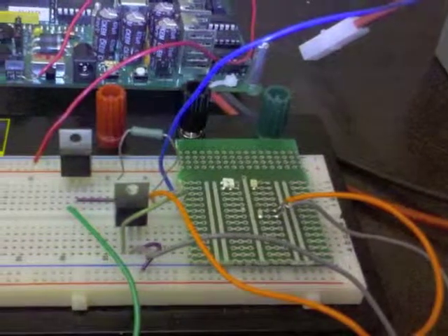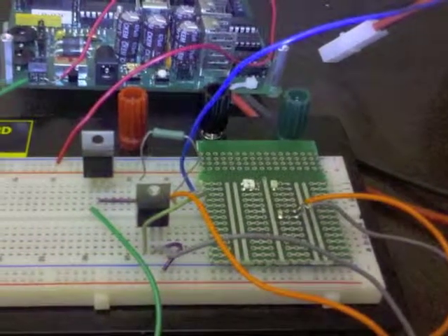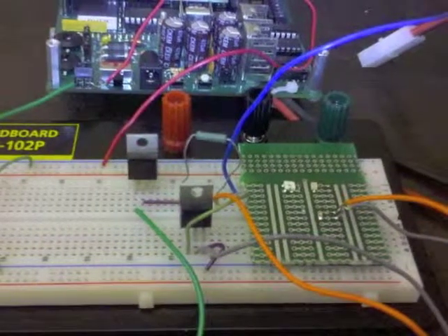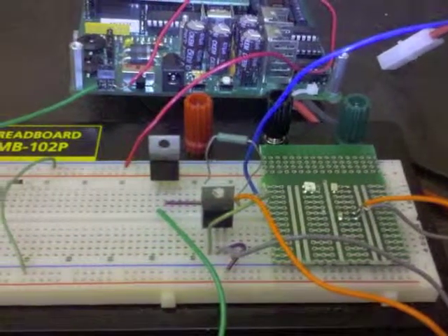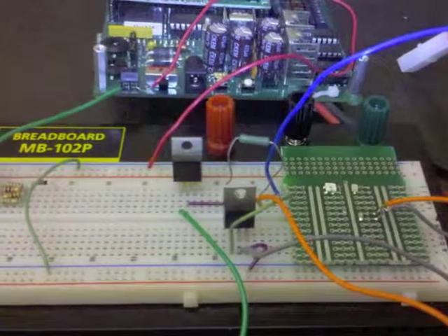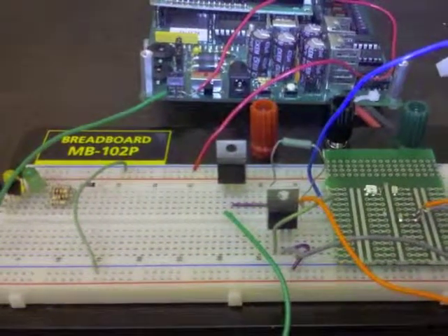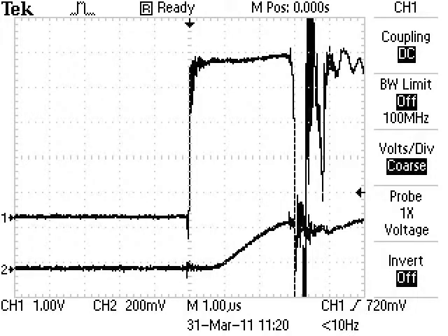Our prototyping had a couple of goals. The first was to determine the shortest pulse that would produce visible light in an LED. Using a phototransistor, it was determined that we could detect pulses on timescales as low as 3 microseconds. From these tests, it became apparent that some LEDs had undesirable transient behavior. Due to these observations, tests are currently underway to confirm which LEDs would be appropriate for the purposes of this